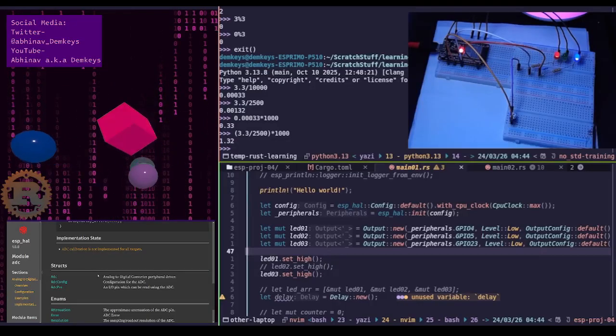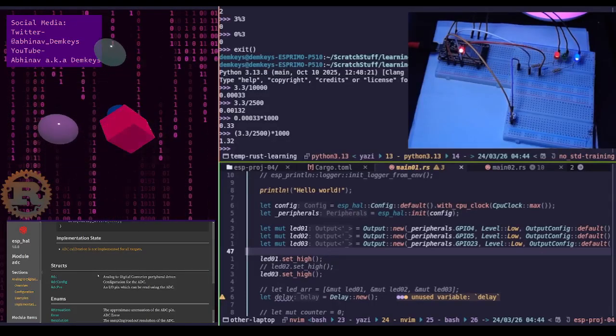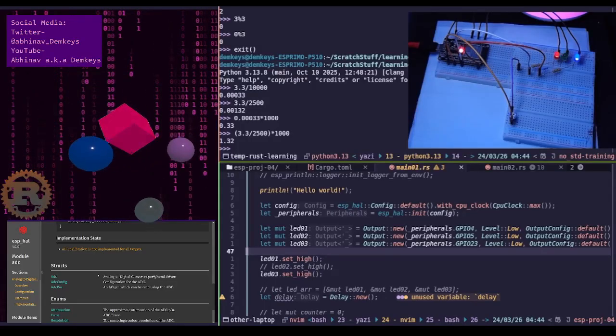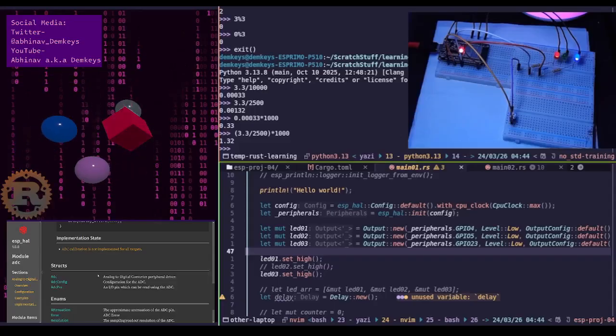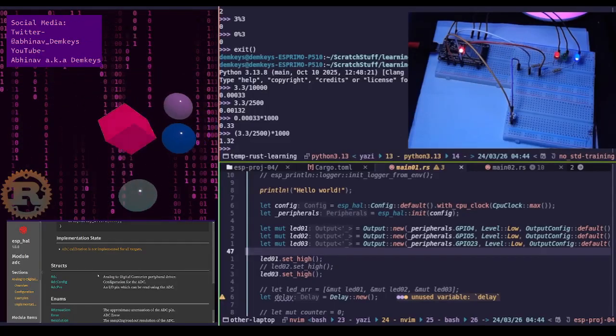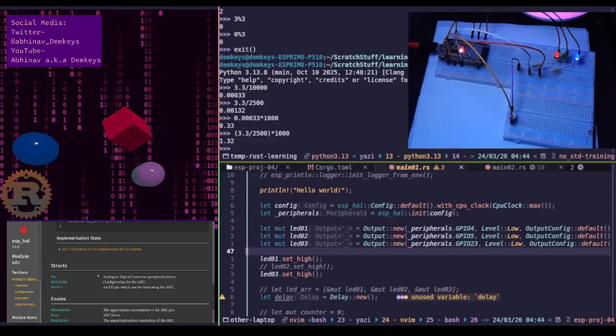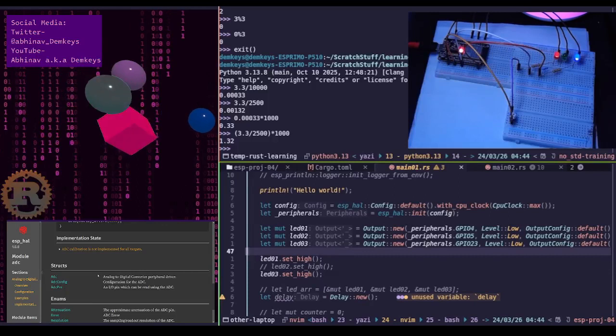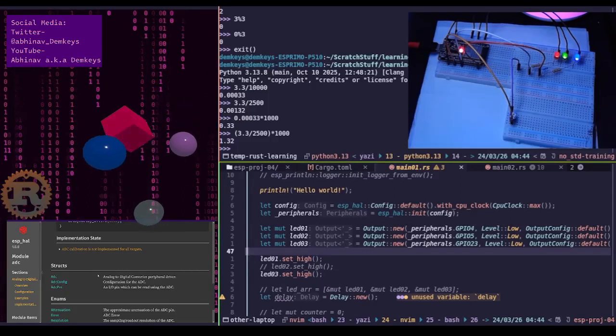Summary: the golden rule. Voltage divider, use it to move signals or data. It tells the ESP32 what is happening. And voltage regulator slash transistor slash PWM, use these to move power. They do the heavy lifting to actually make things happen.